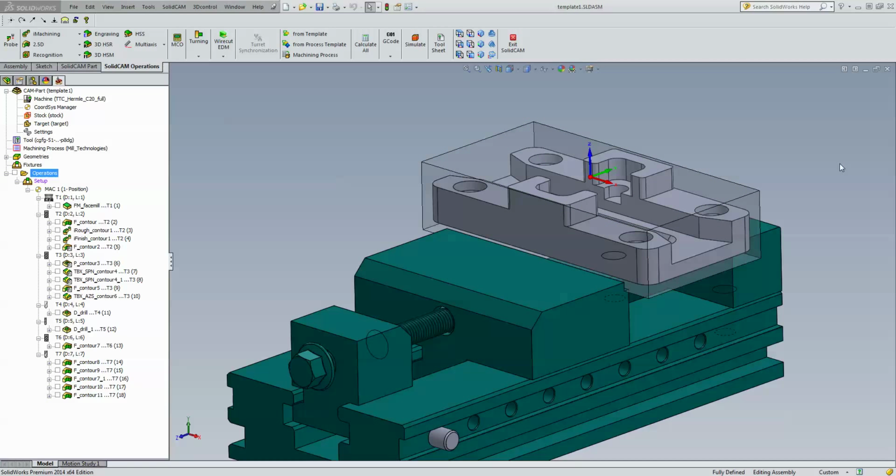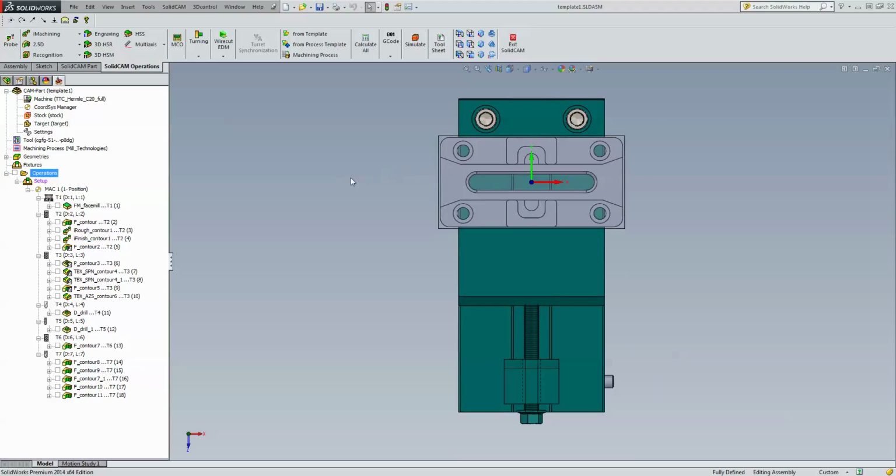In this case, the width of the stock is 104 millimeters, and the face mill is 125 millimeters in diameter. So if I take a look at the top view, I can take a tool and go directly over the center of the part with one pass to clear off all of that material.